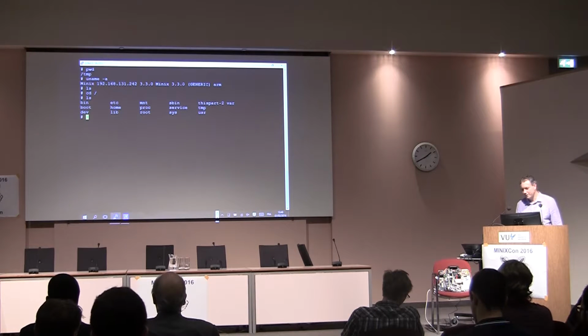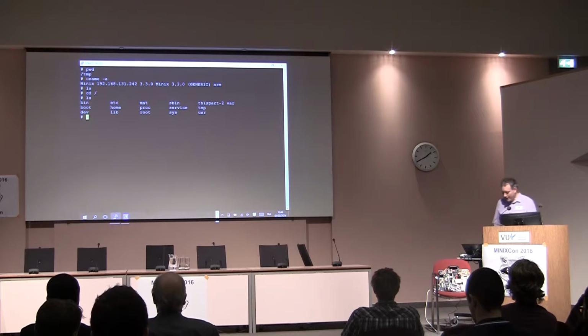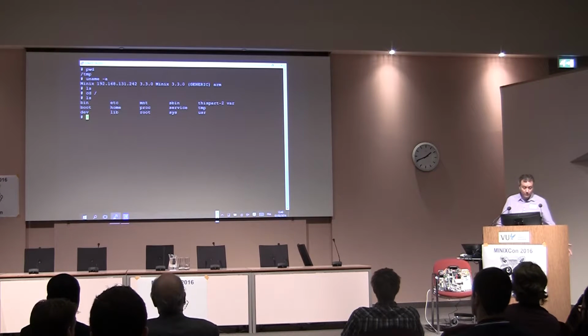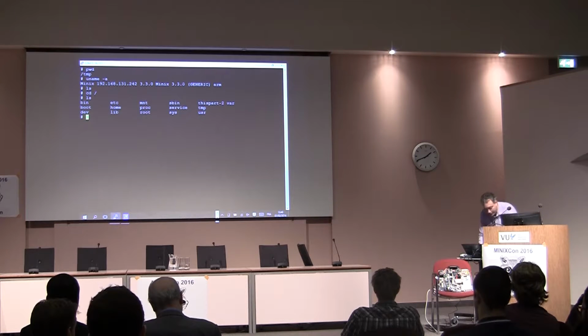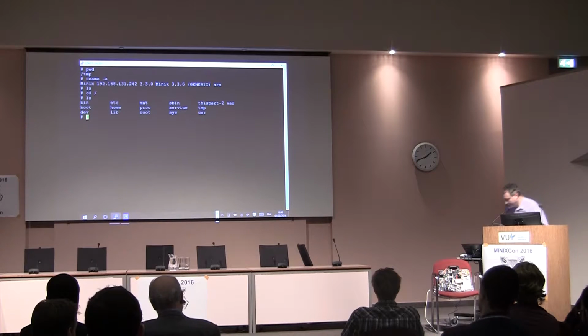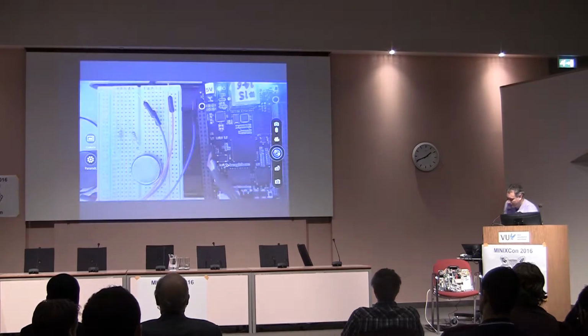So I don't think it has a default network that comes up, and these kind of things are also kind of missing, but this is how it looks running on a BeagleBone or ARM-based infrastructure, just the same as anything else. What we're going to do, though, is create a GPIO pseudo file system, and that's the way that we will access the GPIO pins.